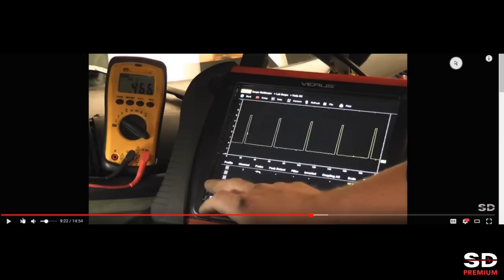See the average? Can you guys see that number? Probably not, huh? That says 0.466. It was like 0.5 something at one point. So between 0.4 and 0.5, this is 0 volts, this is 5 volts. You see the square wave pattern on the screen. Why would the average of a 0.5 volt square wave be 500 millivolts?